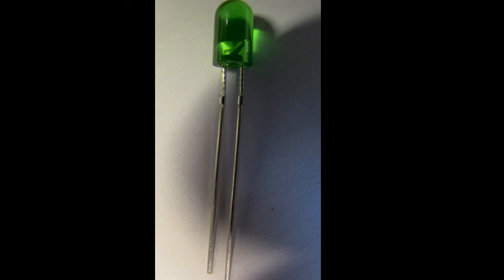On the opposite side, there's a little bit of wire joining your diode over to the anode. So you've got your little diode with its anode and cathode, in this little cup. The cathode is connected to the large piece, and the anode is connected with a little bit of wire going over to the very small anchor down to your anode. So in this case, the cathode is the short lead, the anode is the long lead. So that's internal to your LED.